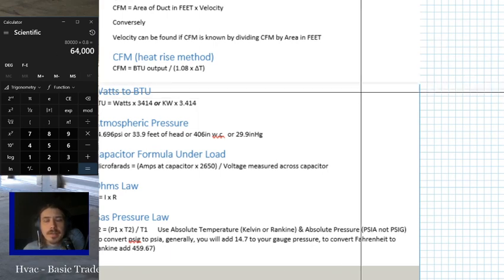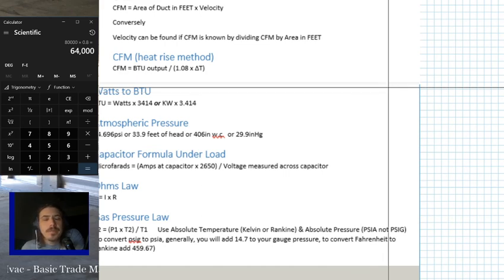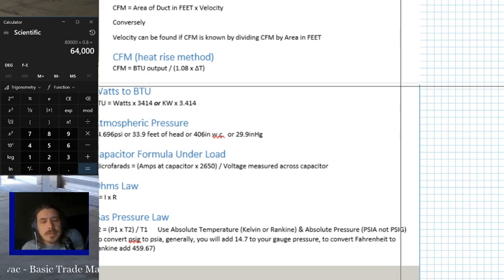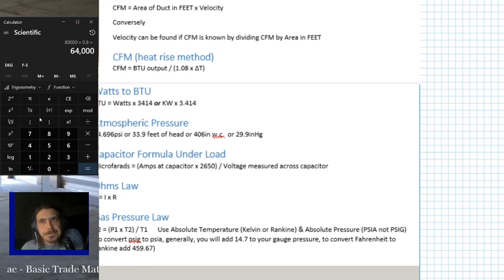So going back, if we have a 64,000 BTU output furnace, and say we measure the return air and the supply air, and we get a 50-degree temperature difference: 120 degrees on the supply, 70 degrees on the return. So you've got a 50-degree temperature difference, and you've got your BTU output. Generally, how I do this is you get two options. You've got a calculator that can do it. We can do 64,000 times parentheses 1.0